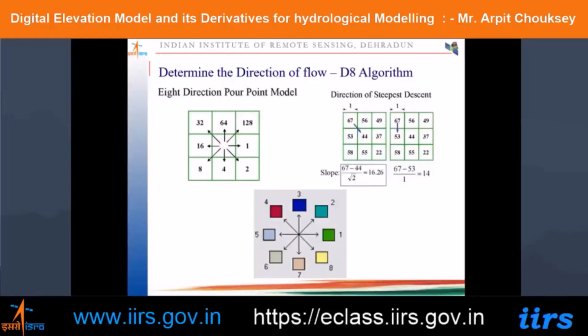In the picture on the very right, the flow accumulation grid is shown. The boundary pixel is 0, 0 or 1, 1. In the middle picture, grids are showing as 3, 2, 2. That means where the 3 is written, 3 pixels are contributing to that pixel. 2 means 2 pixels are contributing to that pixel. Finally, in a cumulative way, at the bottom 24 is written. That means at that grid point, cumulatively 24 pixels are contributing. So that's how the flow accumulation map is prepared.